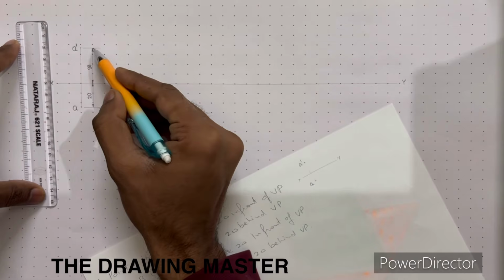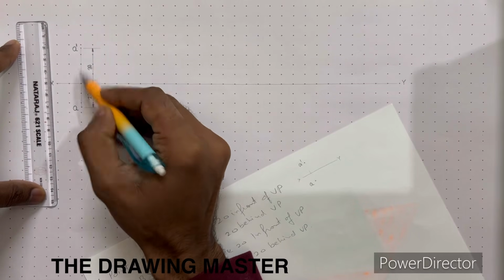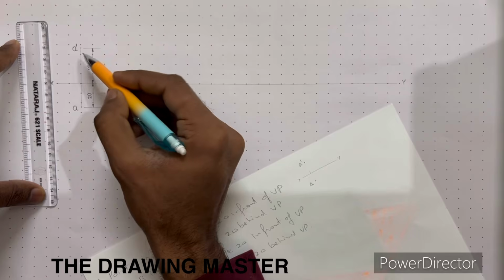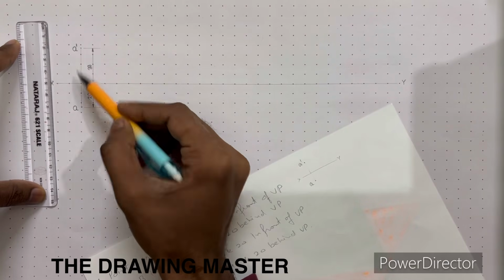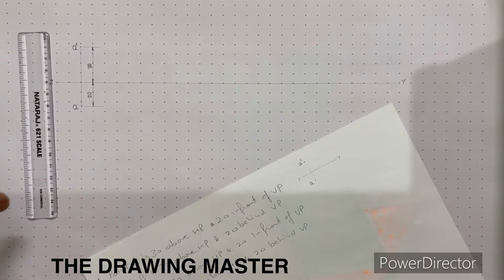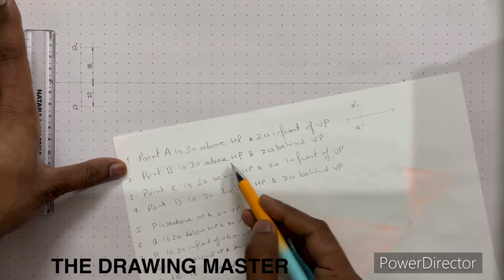If you are writing the A dash on this arrowhead, that is incorrect. If you are not making this projection line and point, it means you are not drawing the projection of the point. Simply you are drawing the dimension line, and that will be incorrect. Follow 3 steps only: reference line, then draw projection A dash A, and then the third step is the dimensioning. Right? Let's discuss the second problem.